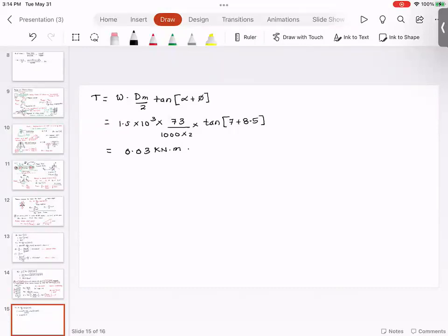So we worked out two simple problems. Now what we will do is we will actually work out the entire screw jack. Any questions before we begin? Everyone understood the key steps? You had to find out the torque, we had to find out the principal stress, and then we have to use these equations to design a screw jack.